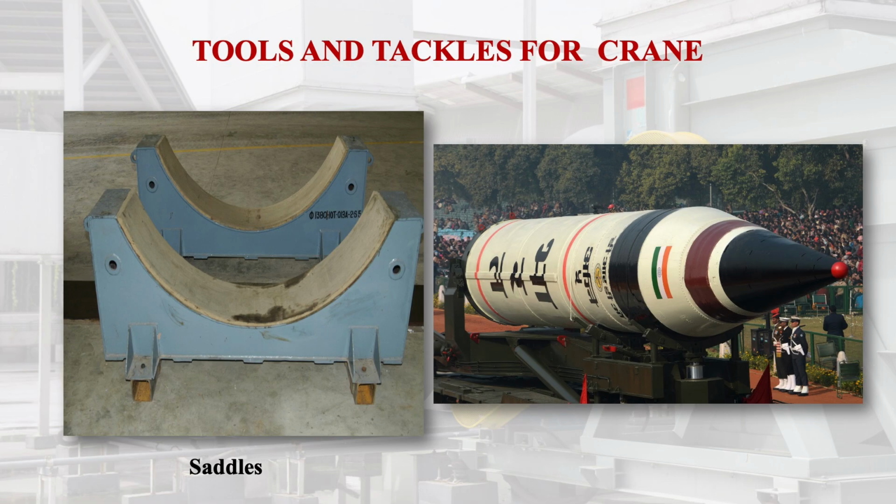Therefore, the saddle should be inspected for corrosion and the stickiness of the felt, as well as welding joints wherever possible. Because a single defect in the saddle should give us enough alarm to replace it. We should not use defective saddles; before use, the defect should be repaired properly and it should again be load tested for safe working load.